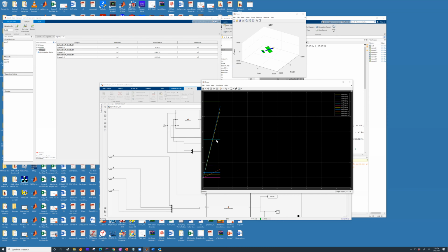If you want to make this a little bit complicated, to make it similar to Zagi, what you will have to do is add a mixing loop before the output. So before these inputs, you have to mix the elevator and aileron as per the mixing matrix that is discussed in the textbook, and I discussed that in the last class. But now, as you can see, this is the Zagi configuration, and it is trimmed.